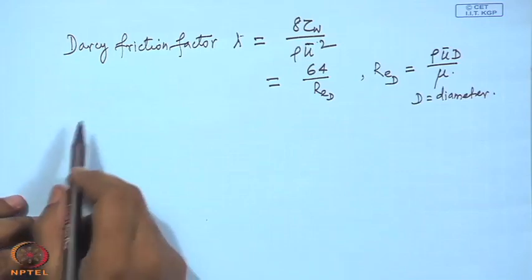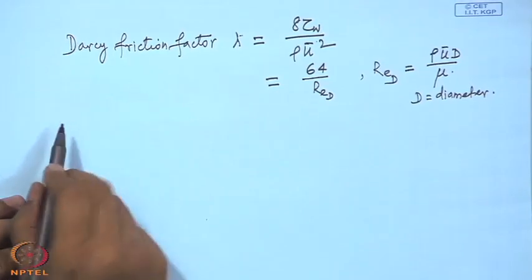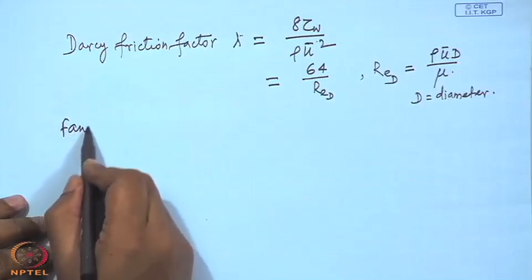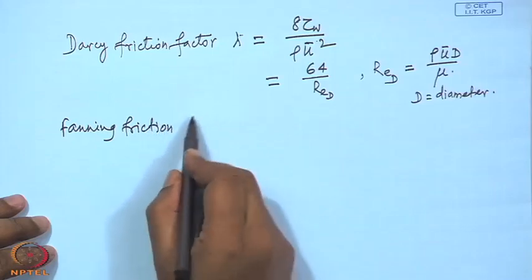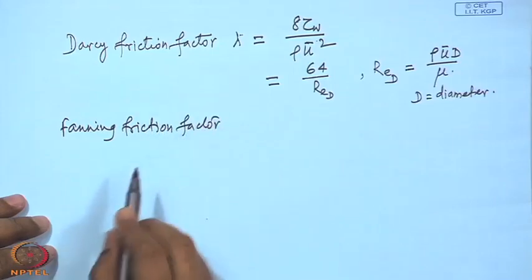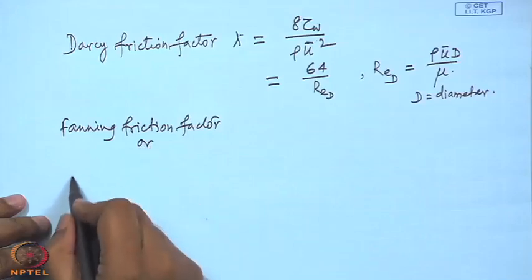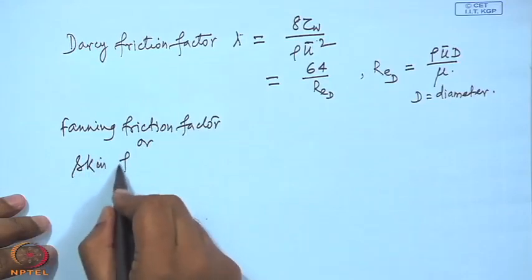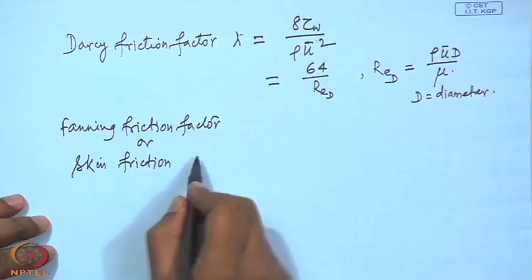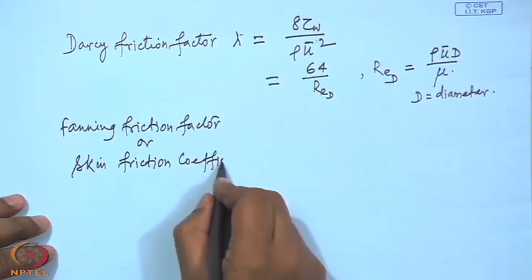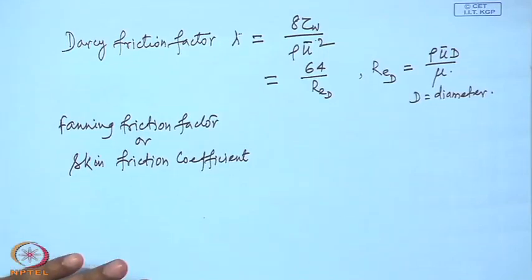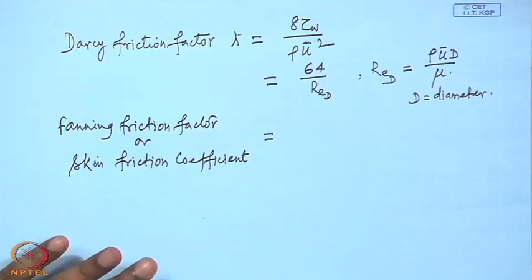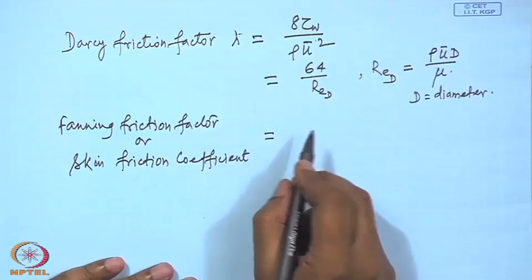Another friction factor is defined, which in hydraulics they call the Fanning friction factor, or we will call it skin friction coefficient. The skin friction coefficient is of course a very popular parameter in aerodynamics.